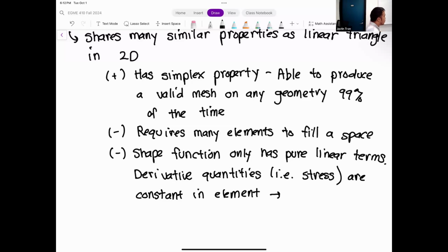So the most notable of which is a phenomenon known as shear locking. Remember, shear locking is a situation where you have constant element cells, and so you end up with a simulation that appears to lock up on itself. So the deformations you get are severely underestimated. Okay. And that can happen if your mesh is not fine enough in particular areas.